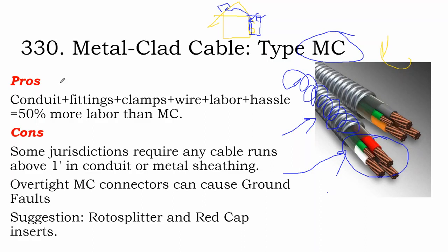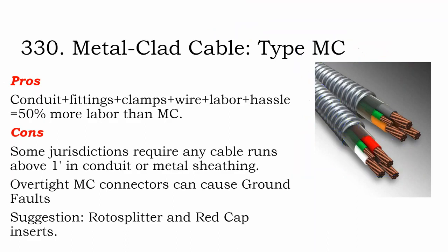But that actually simplifies the installation, because instead of taking your conduit and snaking it over the side of the roof and around the roof and then around the roof again and then down to the inverter, you can just drill a hole in the roof, throw your MC cable over the other side, and land on your inverter. It's much faster, and I feel much better knowing that the cables of the solar array are protected by the home structure rather than exposed to the great outdoors.